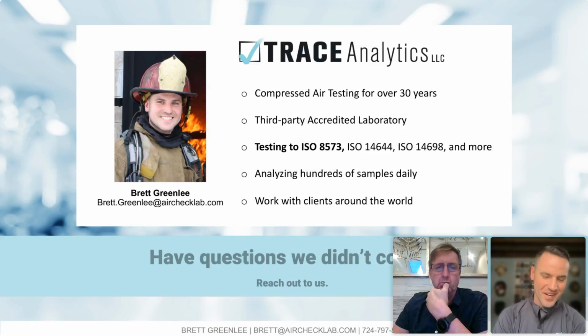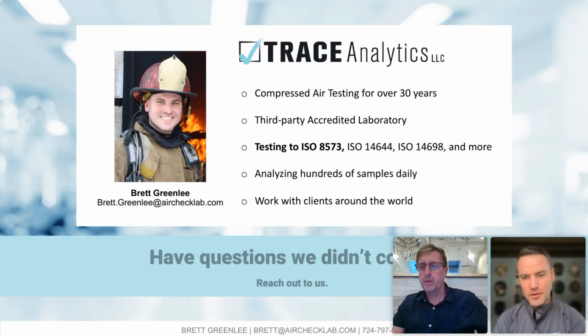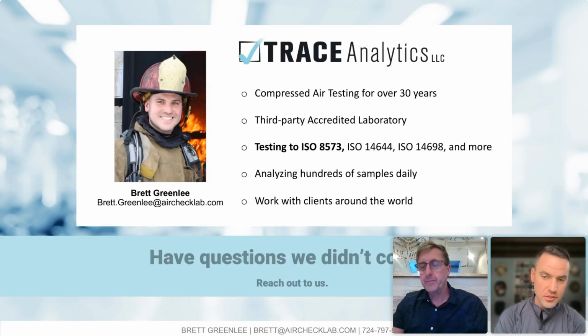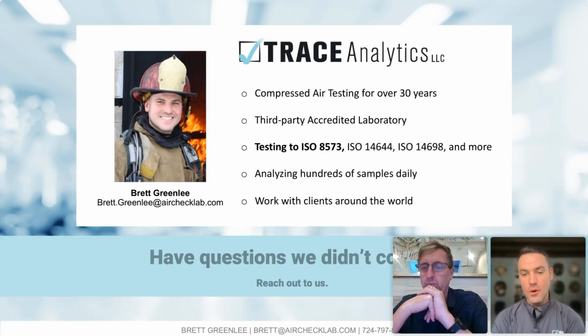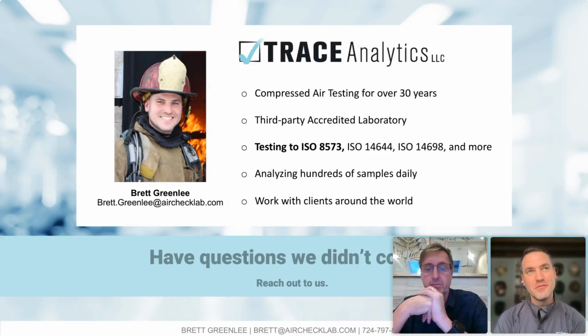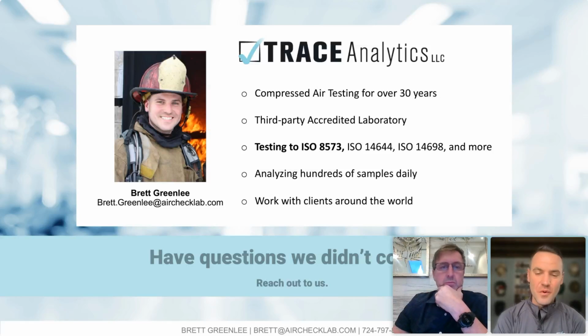And that's got nothing to do with the fact that your tests may come to a laboratory. You can use continuous monitoring or another resource that I showed in earlier slides. However, when you're testing before and after service, that gives you a good glimpse of the redundancy of your system and how it's performing all year round. Obviously, when you take a sample after service, oftentimes it is perfect because your filters have just been changed and your compressor is running at optimal efficiency. But when you take a sample beforehand as well, or ask your technician to, it'll really give you a lot of insight into what your system was doing before you changed those filters.